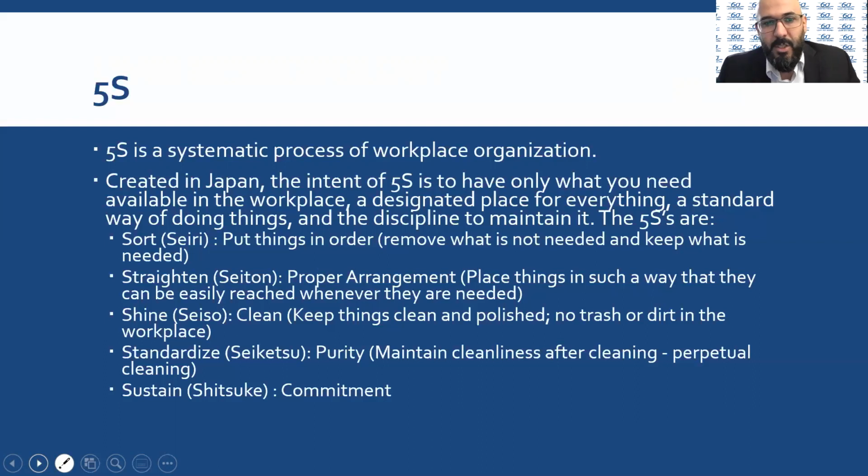The 5S is sort, straighten, shine, standardize, and sustain. Sort: put things in order, remove what is not needed and keep only the things that you're using. Straighten: proper arrangement, place things in such a way that they can be easily reached whenever they are needed.